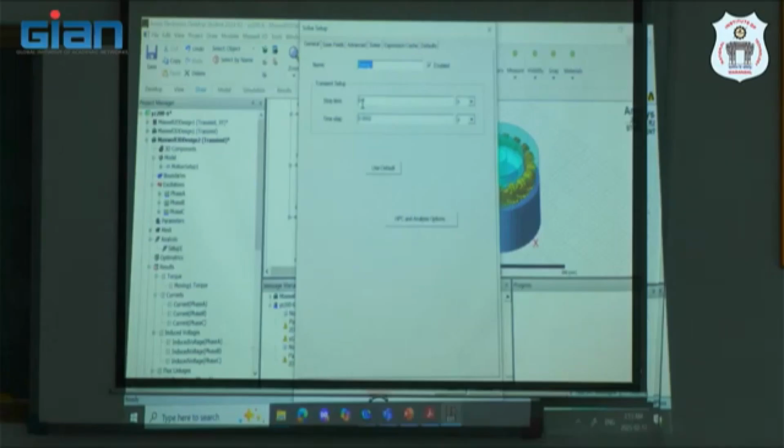So if you are doing a simulation of a 50 Hz system, in order to get a good looking sine wave, you want at least 20 to 30 data points. Right? So 50 Hz in time domain would be 1 over 50, which is 20 milliseconds. So you want to do at least 20 points. So 1 millisecond should be the minimum time step for 50 Hz. 2 milliseconds again 25 data points. So maybe 0.5 milliseconds or 1 millisecond will give you a good resolution. But then you are going to extend your simulation time. Right?